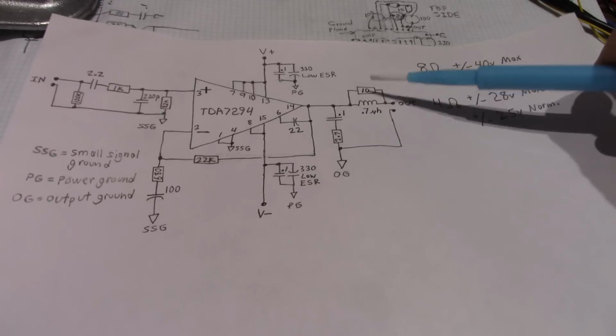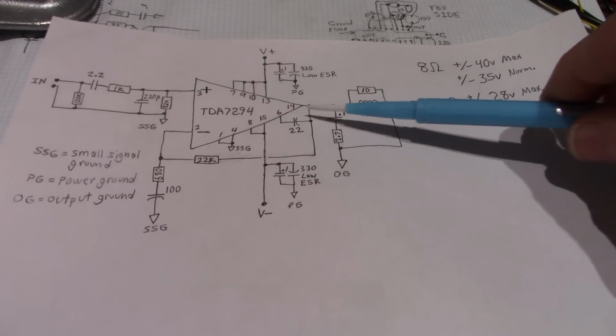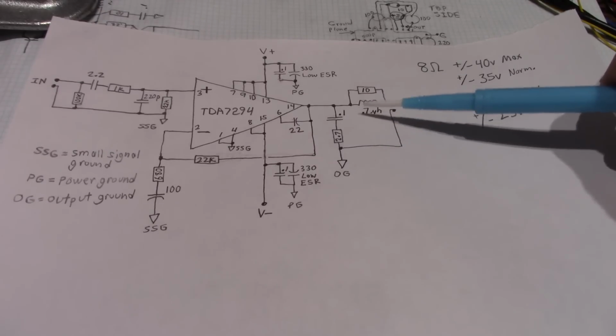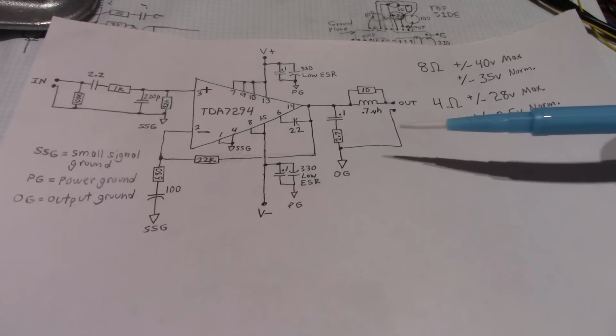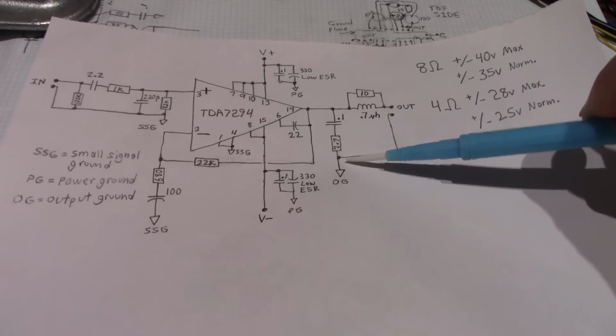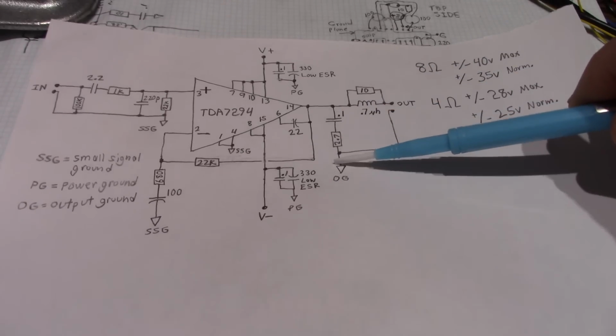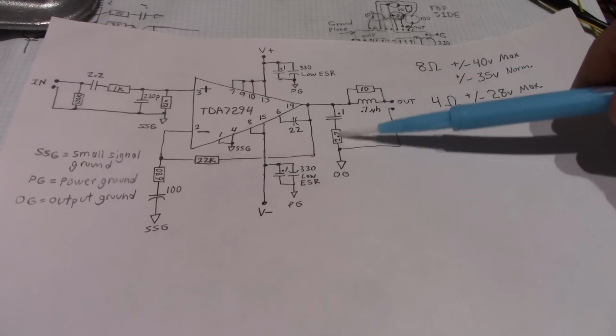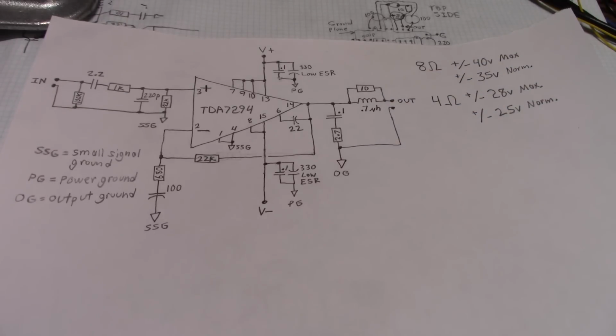And you saw when we did the square wave test, at certain voltage levels we were getting a little bit of oscillation on the negative side of the amplifier. And the Boucherot cell here, I would still have that. I'd always recommend having that in the circuit.